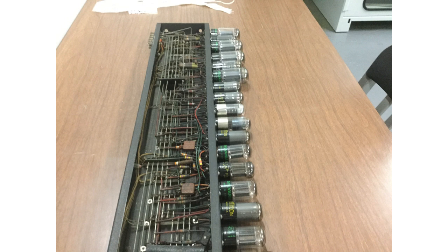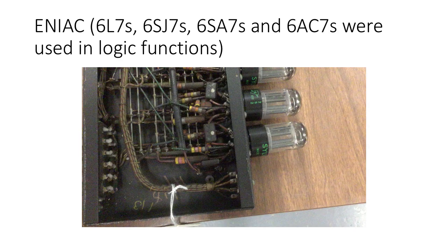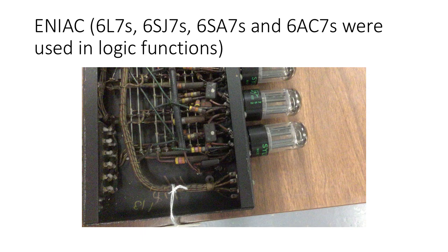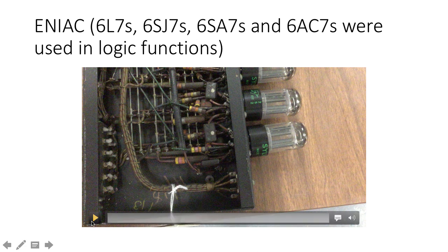When we look at something like this, where we see all these extra tubes, we go, what are they doing? What do they need all these tubes for? Well, there are another 4 tubes used for flip-flops and associated gates for remembering when a carry is required and for implementing the carry. There's really quite a lot of extra stuff going on here to get the implementation going. And what I'd like to do is play a little video for you. Let's see if we can get that running.